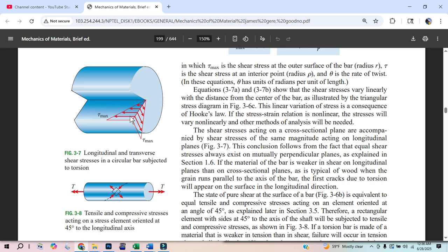For steel it's 0.004. And so if I see that angle, that I know this value, and let's say it's 44,000 pounds per inch. If I see an angle of 0.002, just by linear relationship, you can do the equation on that one. I know this tau is going to be 22,000 pounds.